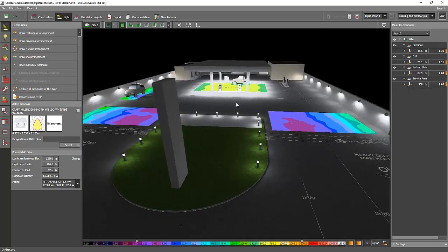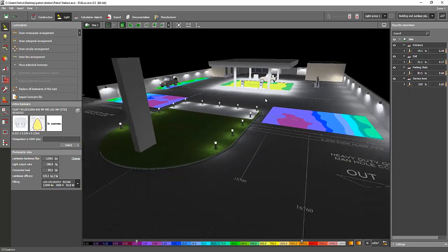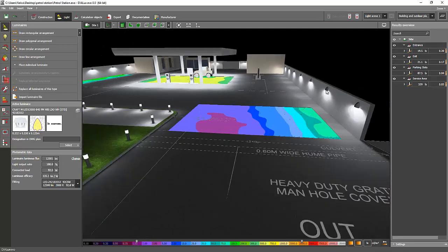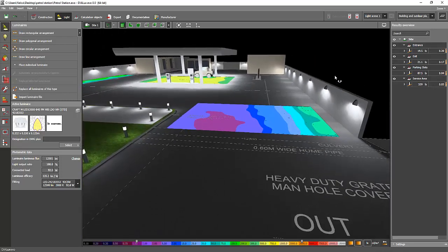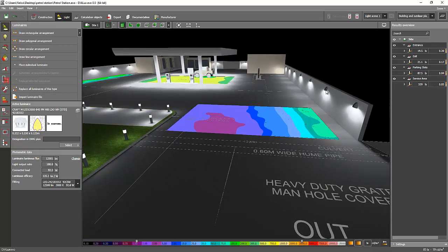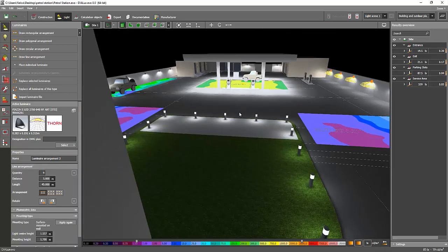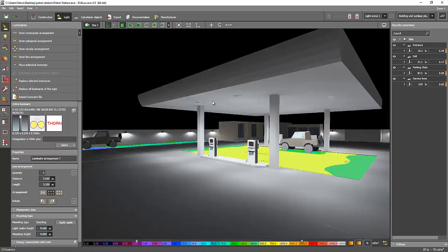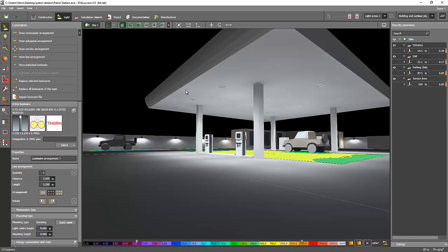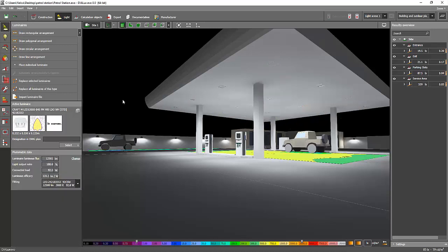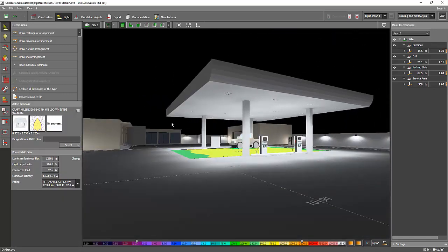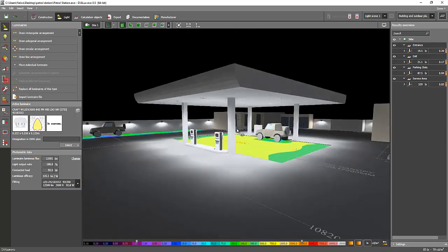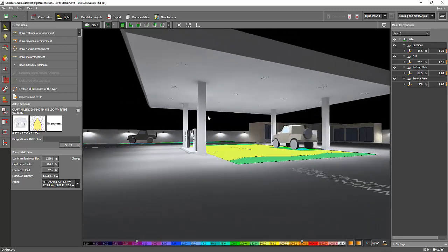So one of the considerations in lighting design for a petrol station is to limit the light pollution. So what I did is, instead of putting a street light or area lighting, I just put a wall-mounted luminaire and bollards on the entrance. And of course, the correct luminaire for a petrol station should be IP65 and everything. And is it really necessary to be explosion proof for a luminaire in a petrol station?